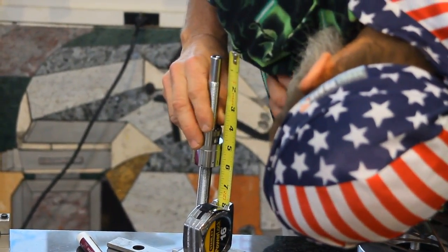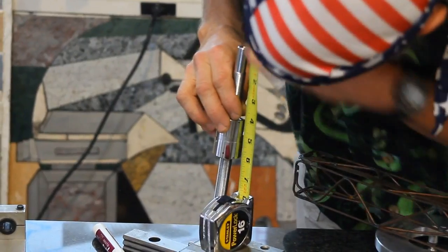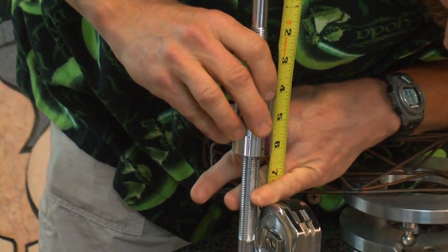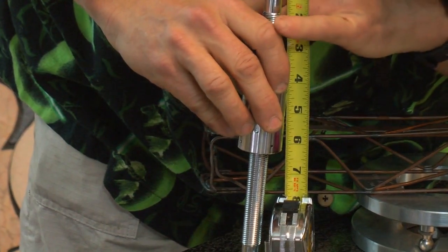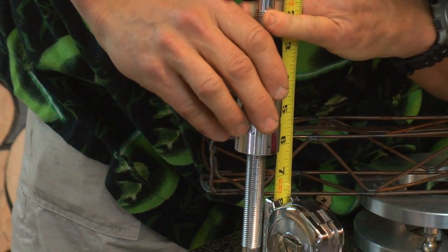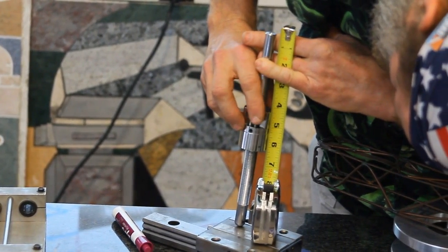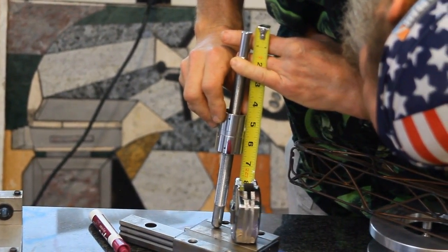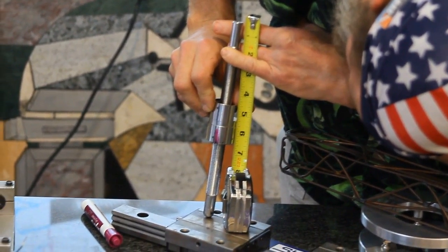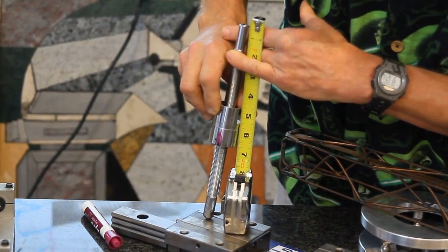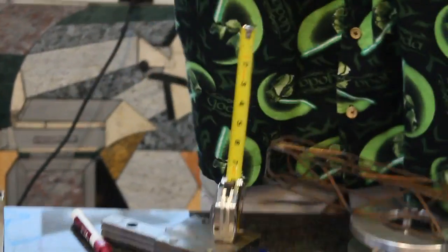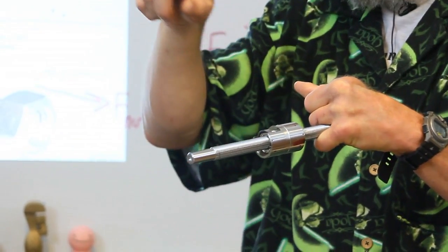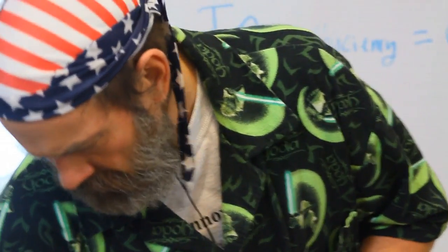And we're going to set this up so I am right at the number 6. Okay, so I'm going to rotate the nut through one rotation. And as I rotate through one rotation, it moved about, let's say 3/8 of an inch, a little less, about 8 millimeters. Okay? I would say it moved about 8 millimeters. This means that when I rotate the nut through 360 degrees, it moves 8 millimeters.